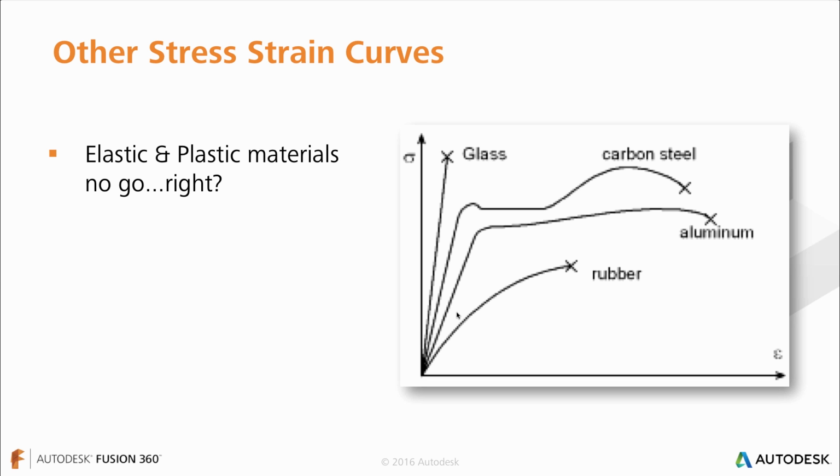Back on the stress strain curve discussion. Other materials don't behave with that straight linear initial part of their stress strain curve. Things like elastic materials and plastic materials don't do that. You can see a rubber example presented on this list that also has aluminum and steels. You can use a linear assumption, like doing some curve fitting to figure out what a straight line representation might be. Although these materials are not recommended for a linear statics problem like the one we're going to show, you can still use this information to get some idea of how your model might react.